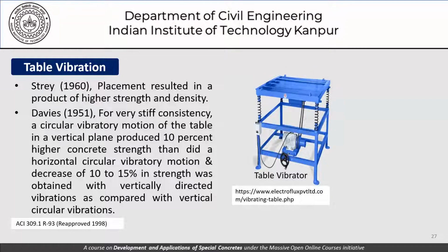So you can imagine that what we are talking about here is a table with springs, and we are trying to vibrate this table using a motor. The weight is fixed to the table. So we can try to have the motor in different configurations, have different stiffnesses here, and finally come up with a design which will help us optimally vibrate and consolidate the concrete samples placed on the table. It can be one sample, it could be a set of samples, whatever we have.